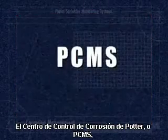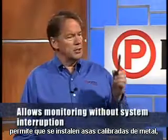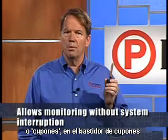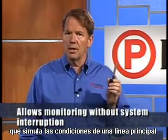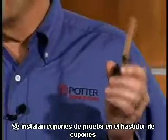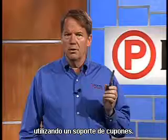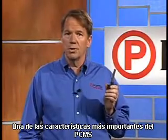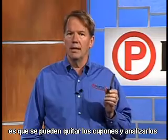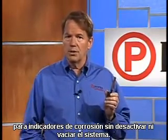The Potter Corrosion Monitoring Station, or PCMS, allows calibrated strips of metal called coupons to be installed in a coupon rack that simulates the condition of the fire sprinkler main or branch line. Test coupons are installed into the coupon rack using the coupon holders. One of the most important features of the PCMS is that the coupons can be removed and analyzed for signs of corrosion without disabling or draining the system.